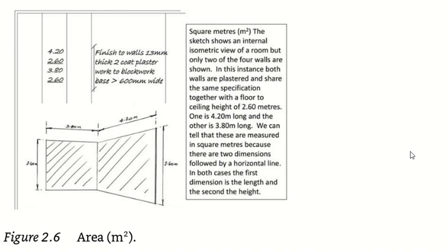Will it affect the quantity of plaster? No. Width of the block, third dimension. You are doing plaster here, it will not affect. But we are writing it because the standard method says that you have to write the width. And it should be divided according to the width of the block work.